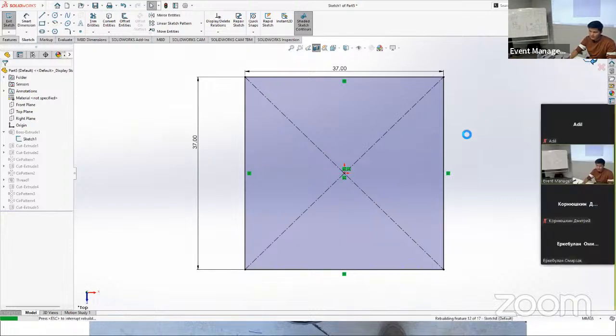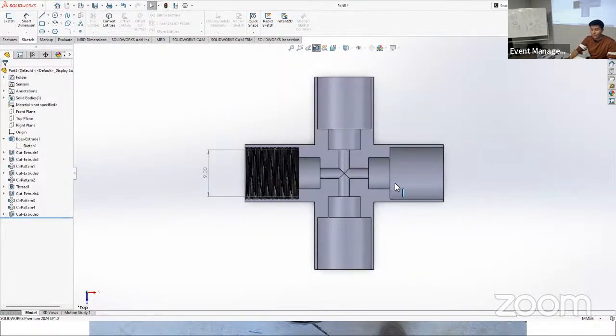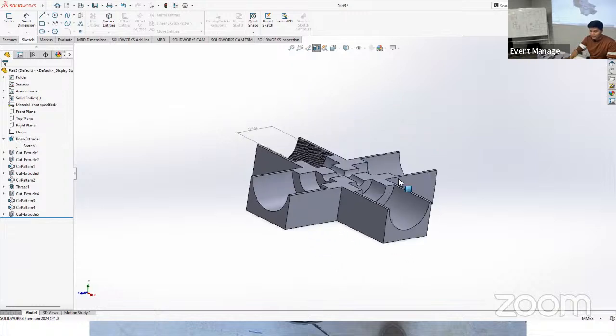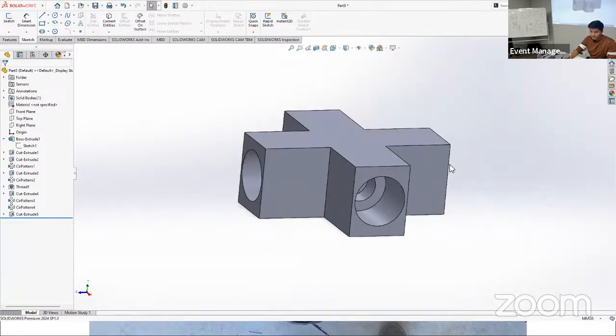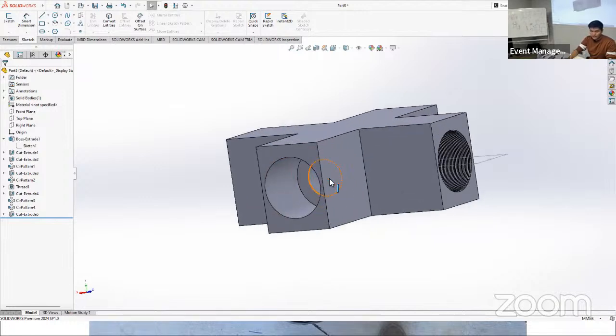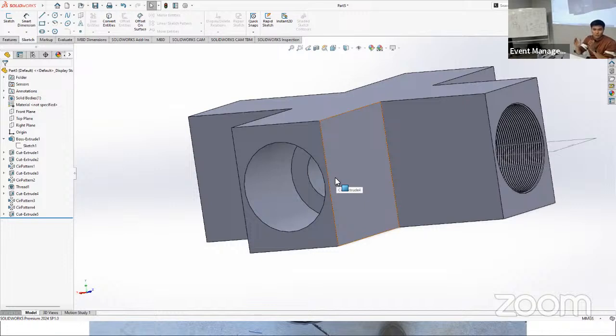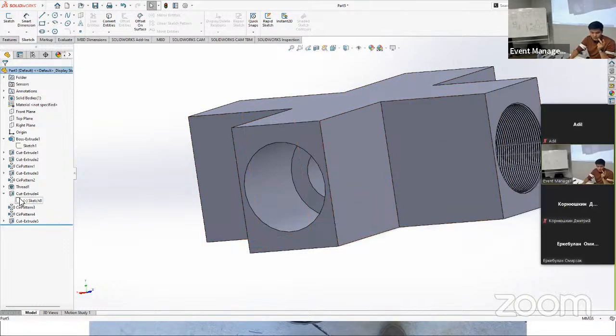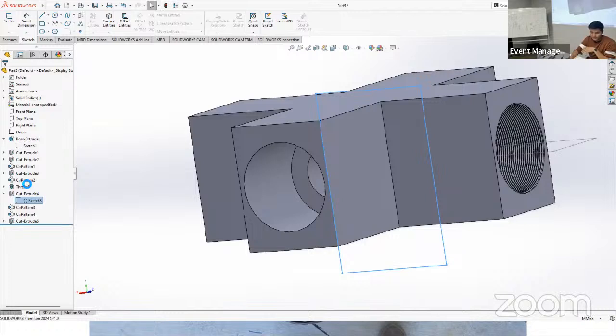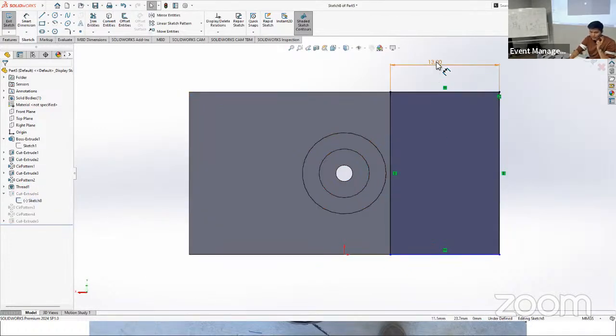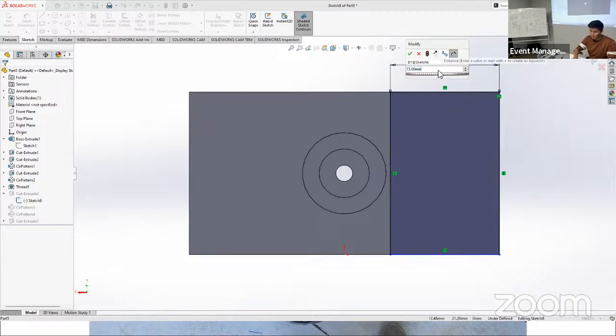Okay, now let's give it another few minutes for it to sync. Oh, okay. So now it's showing us that it's in that form, and that thickness went crazy small because we trimmed 3 millimeters. So it's going to be 1.5 millimeters from each side. So our cutoff corner should be actually less by 1.5 millimeters. So it's going to be like 13 minus 1.5.